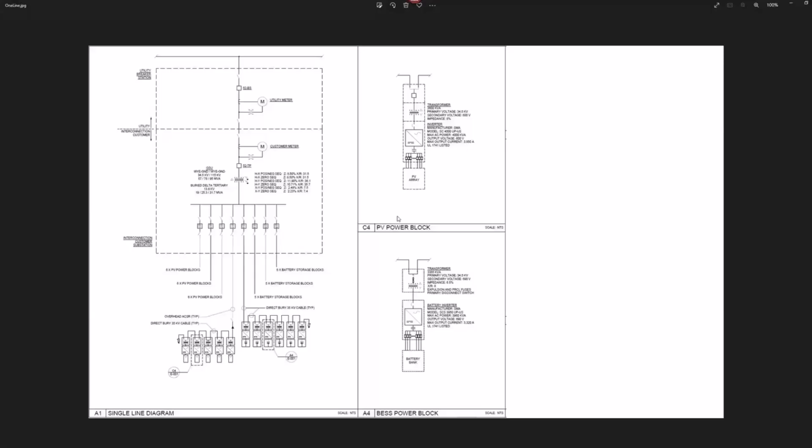And as we all know, or maybe not all of us, but at least some of us may know that IEEE 519 was just released in 2022 back in August. So starting from that time, there will be a decision tree, which we'll talk about later in the IEEE 519. So IEEE 519 will no longer be the only standard applicable to the industry, especially for renewable power plants.